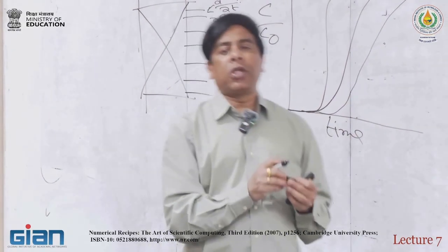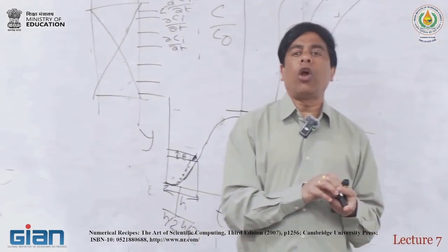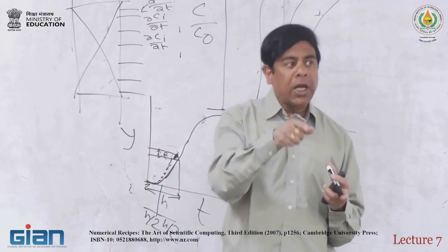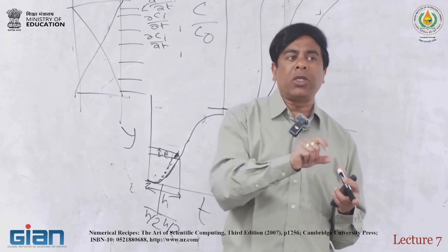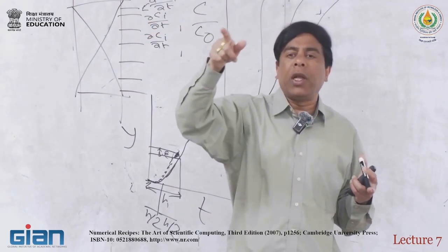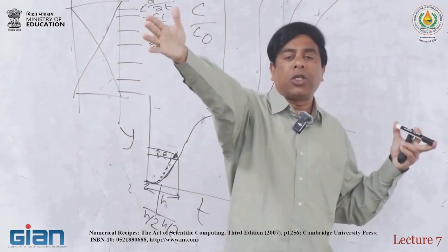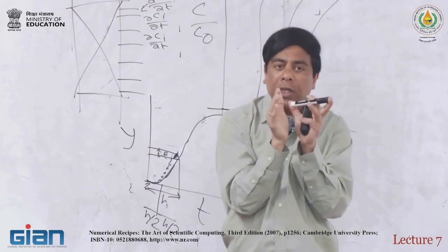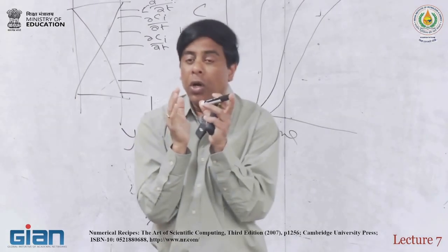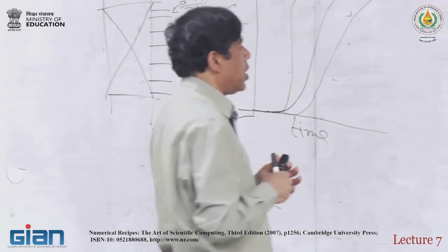So all these solvers, these approaches, if you have used MATLAB before, these things are not available in MATLAB, but you will see in Aspen this option is there. It lets you set a minimum step size and a maximum step size. This is what it means: as a user you are saying, I cannot let you take a larger step size than this, while the minimum step size is saying you keep cutting as needed until you reach that lower limit, right?